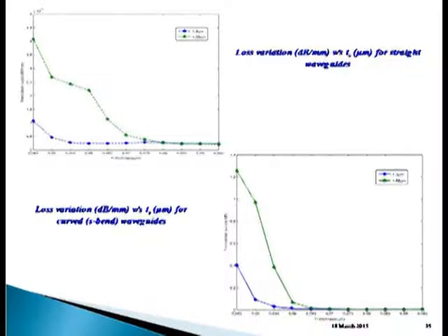So they calculated the relation between these two powers Q1 and Q2 and the earlier powers P1 and P2, and then checked the effect of this power variation on the crosstalk performance of the switch. Their switch was working with a switching voltage of around 7.3, but the new thing was the effect of the power imbalance in the interferometric arms on the performance of the switch.